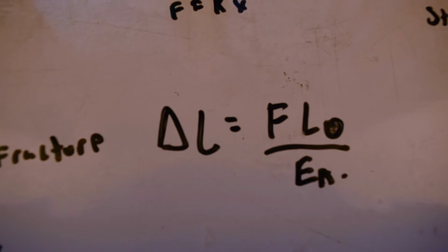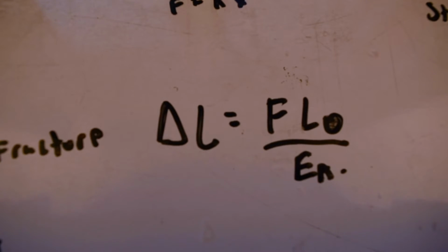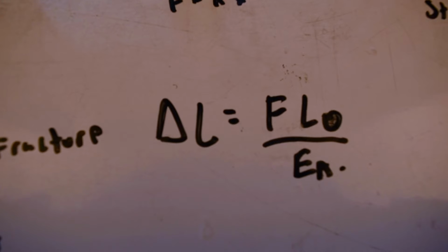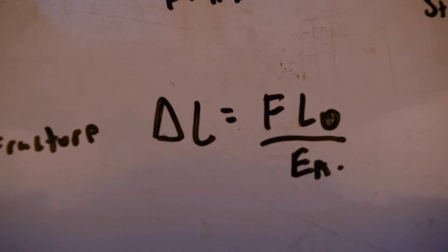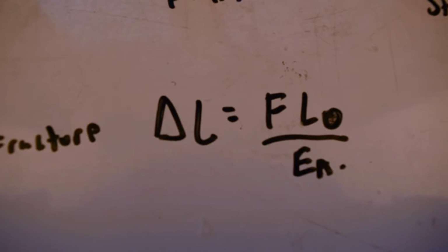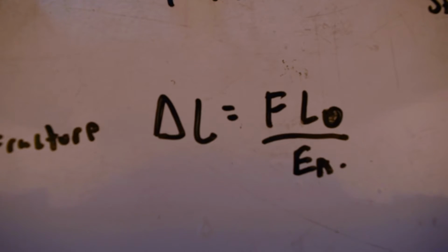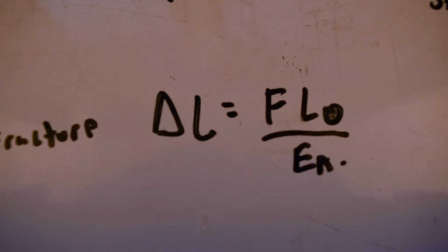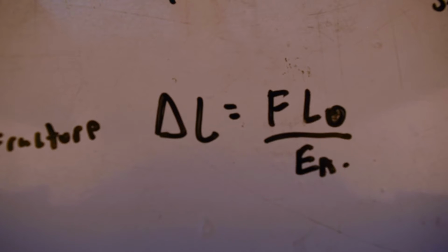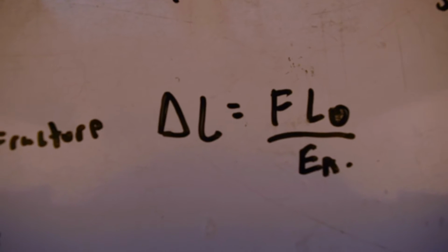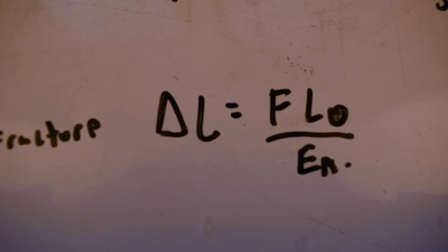Elastic modulus is like a K value, but every specific material has a specific E value, and wood has a specific E value. But putting the math aside, it's fairly obvious that as force increases, longer length is needed. Or if you rearrange this equation, to minimize the force exerted, you will need to maximize the length. And that is exactly what I did here.